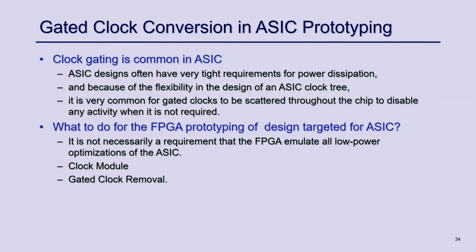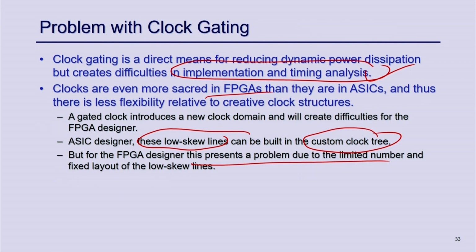You also remember that FPGA is a very power hungry module, where power optimization does not work, because it is a redundant technology, right. It has reroutable interconnections and reprogrammable logic. So, all are kind of redundant circuits. So, FPGA in general is very power hungry, and low power techniques for FPGA do not work. So, people who are working on FPGA do not bother much about power issues for an FPGA target.